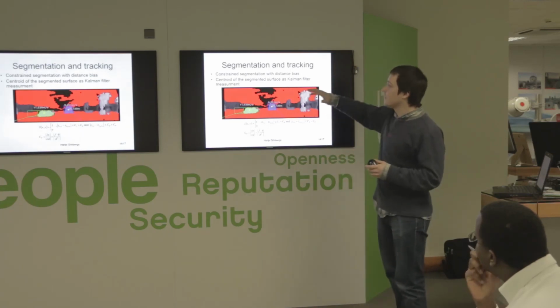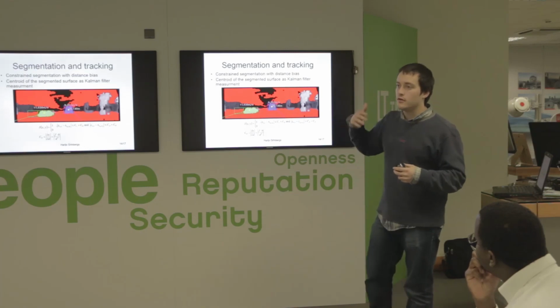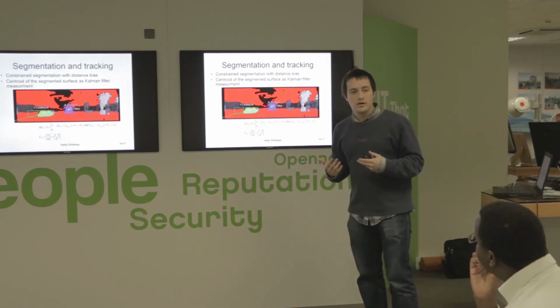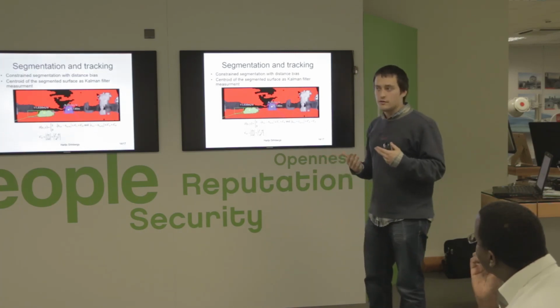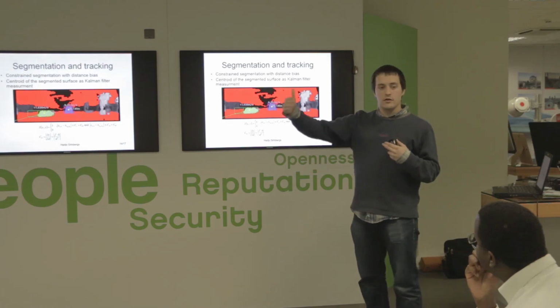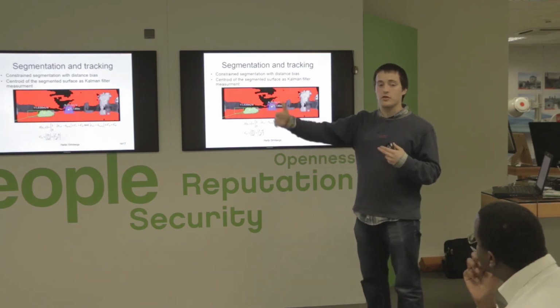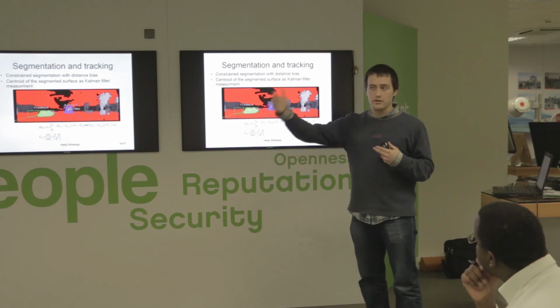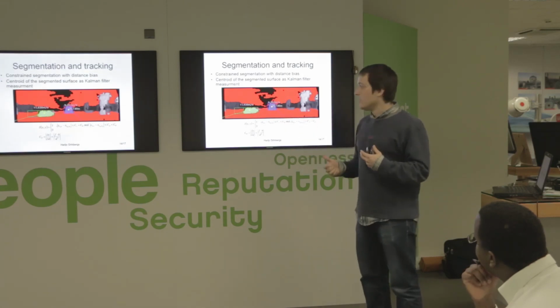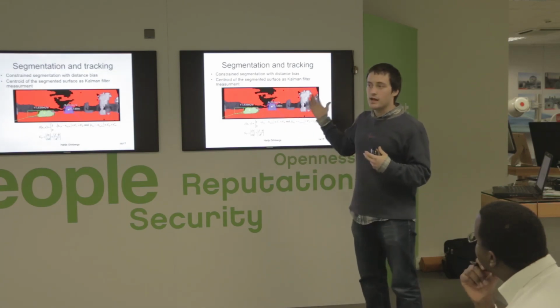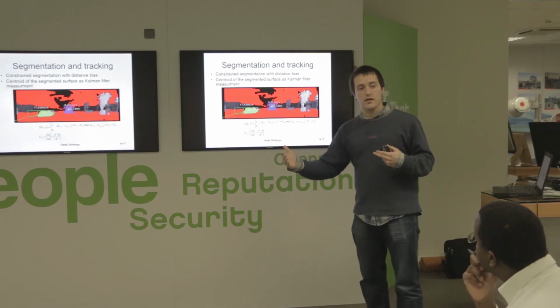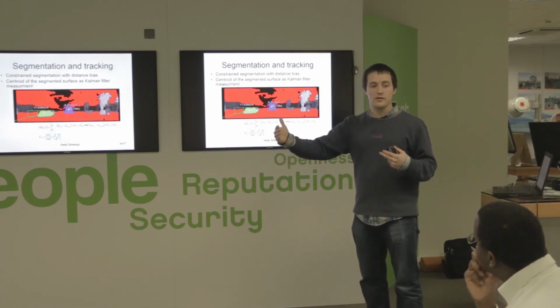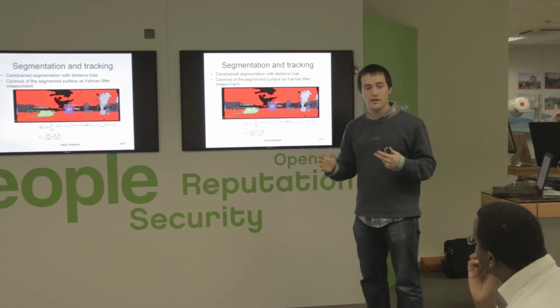Then I have to take into consideration the noise, because in stereo vision the error in calculations is exponential, and it grows pretty fast. For example, in my case I could track a car to 45 meters, but at 45 meters the error in the point calculation is about 6 meters.